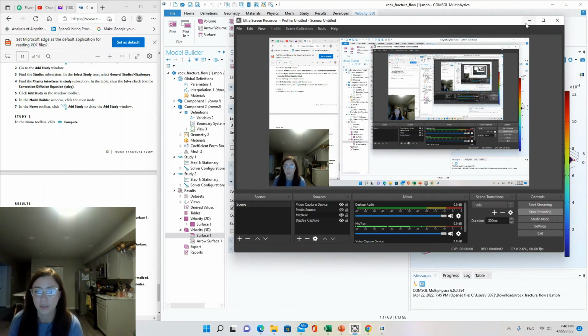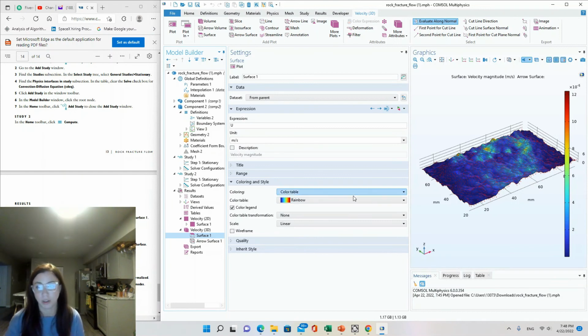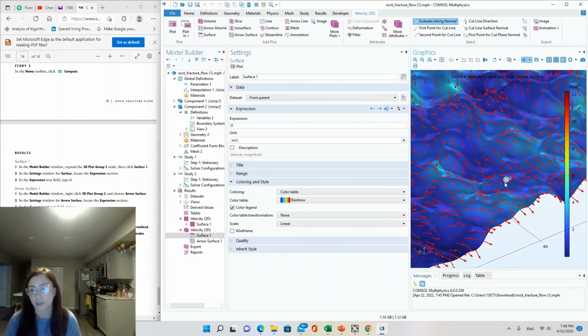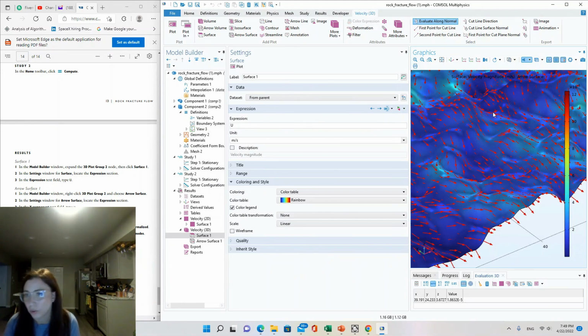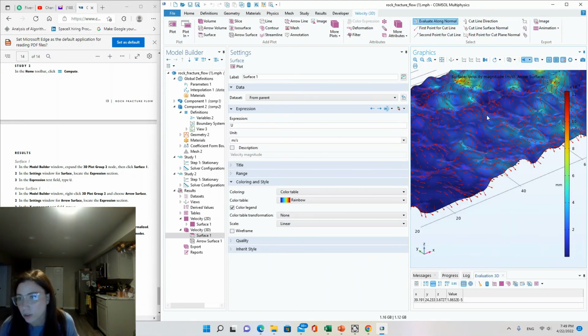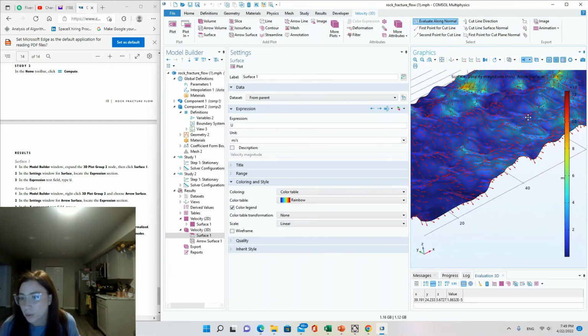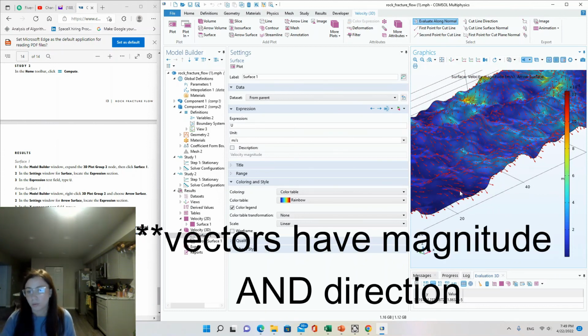Alright, well, I'm going to have to debug later, but we'll just use the downloadable file from COMSOL since we're almost finished here. It's just this results paragraph. So I'll just use the file that works, which basically is just using that plot to add vector arrows for the surface plot of the velocity magnitude. So you can see a 3D plot with the magnitude of flow represented as these red arrows.